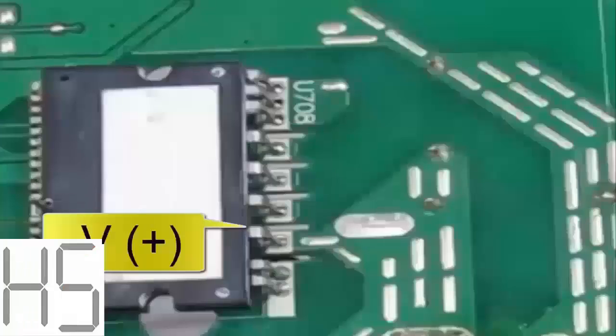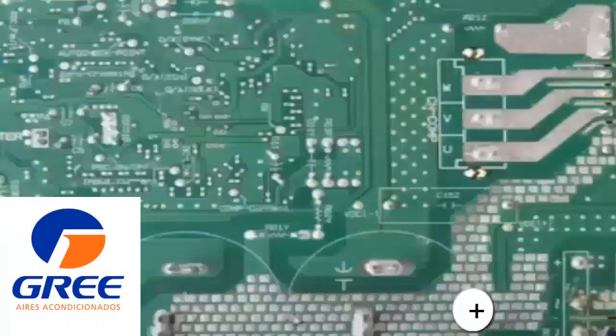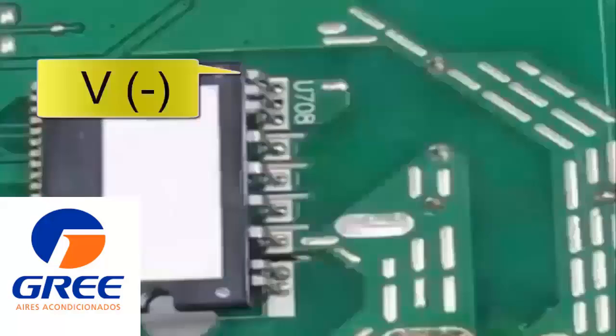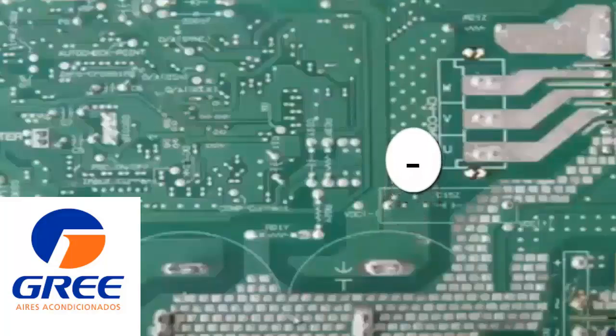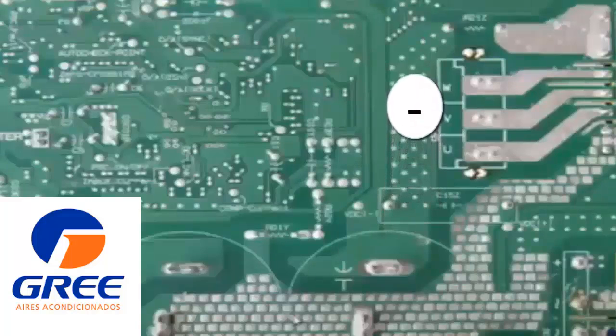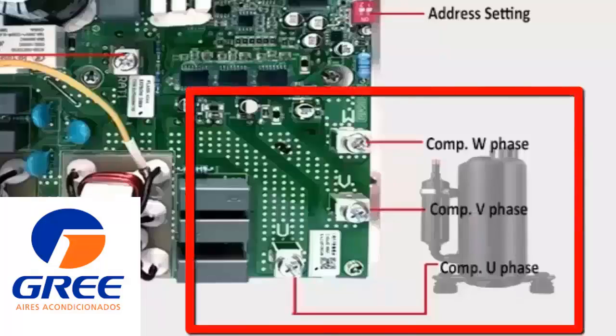3. Positive power supply. Identify the high voltage positive power supply of the IPM electronic circuit by tracing the positive track from the largest high voltage capacitors to the IPM electronic circuit. 4. Negative power supply. Identify the negative track from the capacitors to the IPM electronic circuit by tracing the negative track from the largest high voltage capacitors to the IPM electronic circuit. 5. Identify the output points U, V, W. These can be identified by following the tracks from the compressor connectors to the IPM electronic circuit.